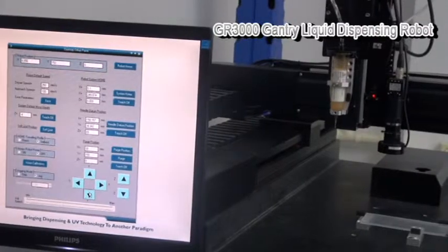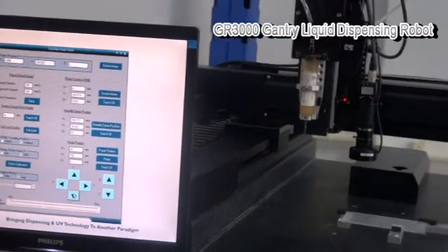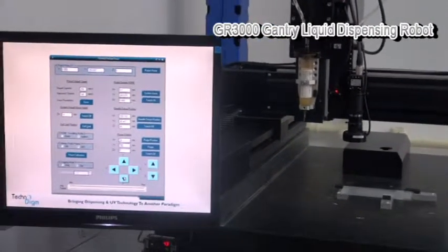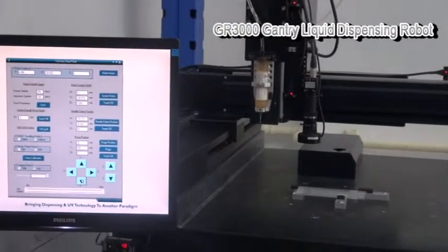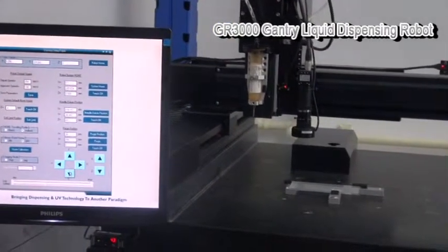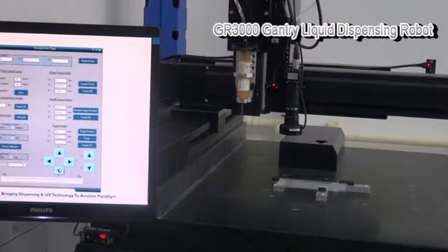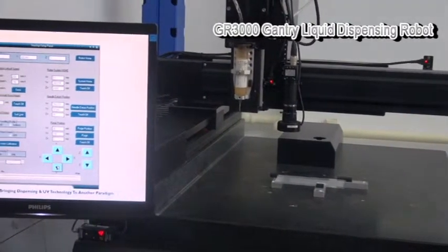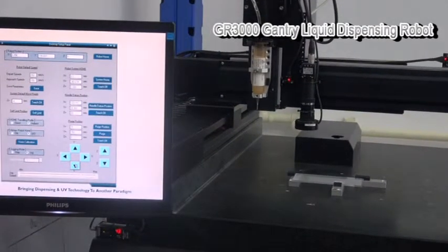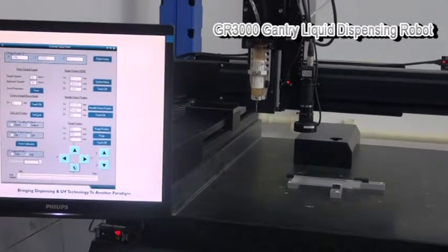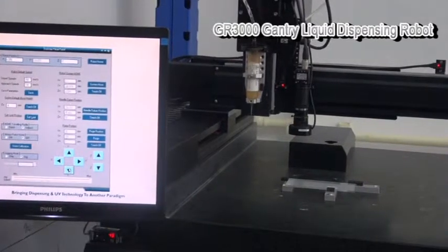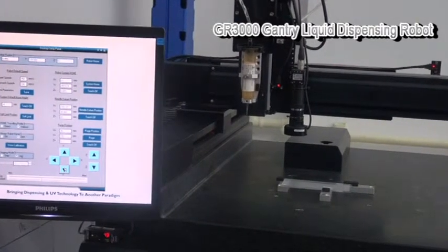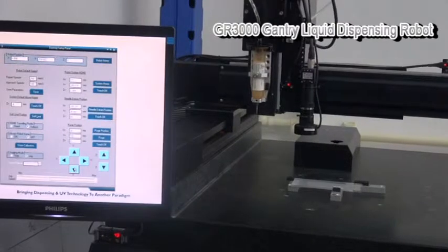I will show you. Basically that is a system setting such that any movement of the robot as a whole, not the robotic movement during dispensing. Any of the system movement means moving from one point to another point. That is the height that you move to. It's not for dispensing height. It's for any other movement except the dispensing.